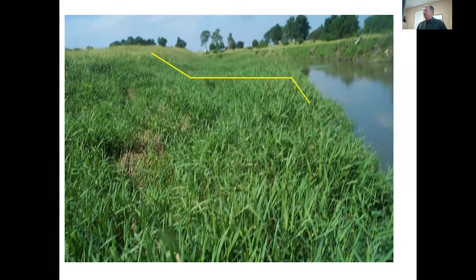And it's sort of reestablishing its own floodplain at a slightly lower elevation. So this can happen even within the channel banks themselves, where it puts point bars, where it tries to reestablish a new bench inside the channel banks. These are all indicators of down cutting in the past and indication of the channel evolution model stage.